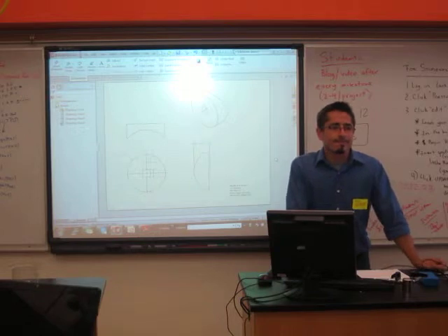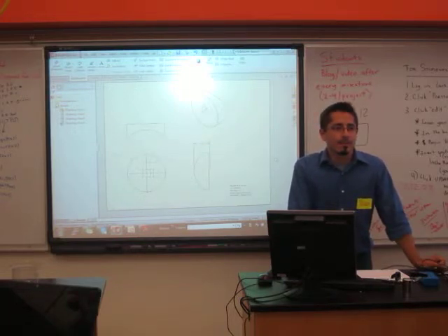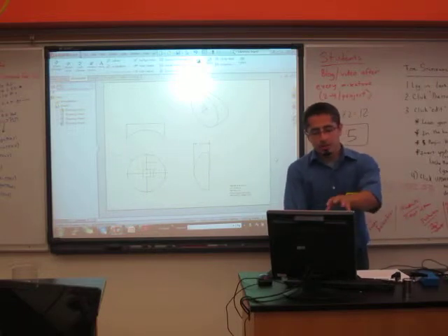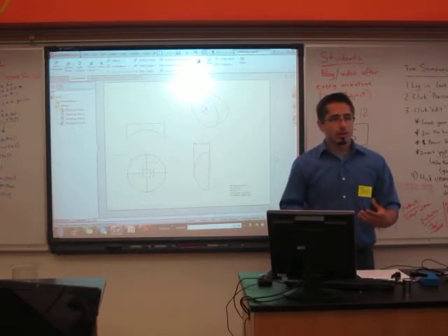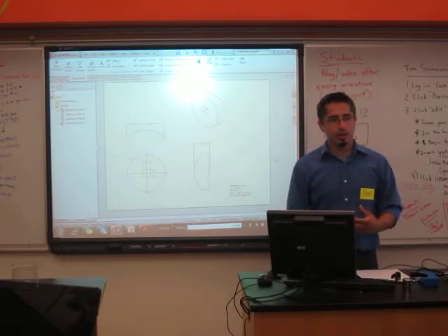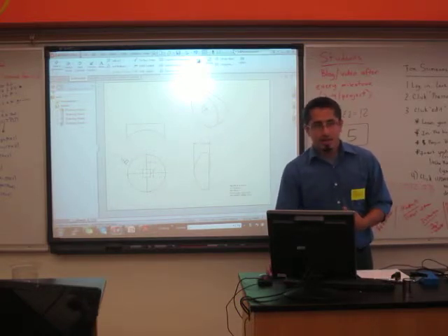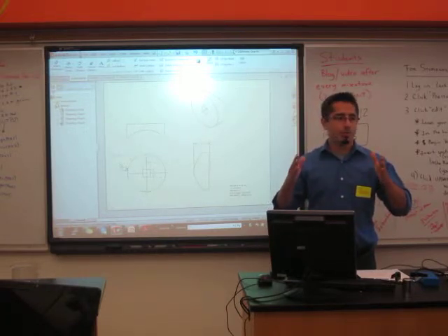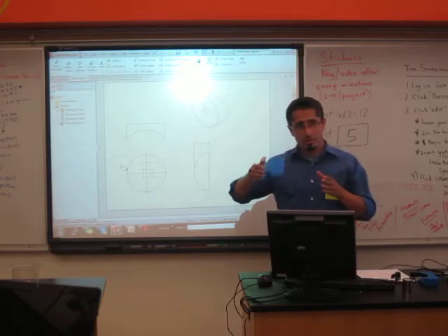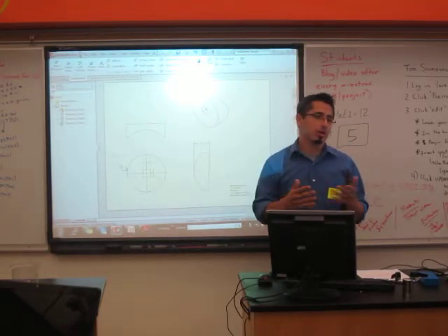Wouldn't it be much easier and more accurate if they were just able to use the file with the 3D model in it than to have to look at blueprints? Yeah, but a lot of times you can use a 3D model, but by doing this blueprint here, in manufacturing, they'll take the blueprint, they'll make the part, and it's not going to come out to that blueprint perfectly. That 2.5000 is not going to come out to that. It might come out to 2.508. So use the blueprint as a way to check what it's supposed to be. Because the 3D model is all vector based, so the numbers come out exact. It's 2.500000000.